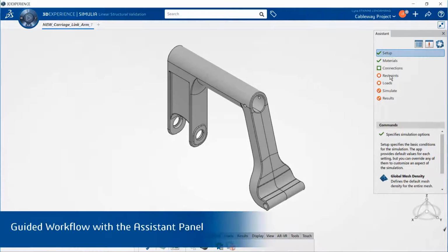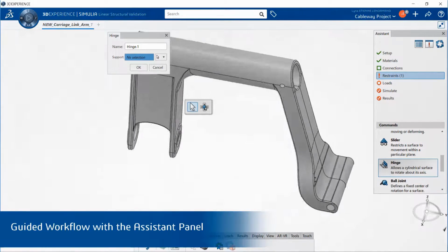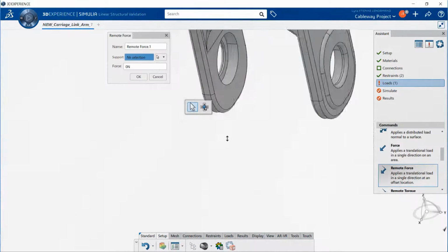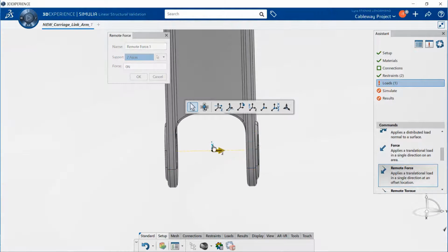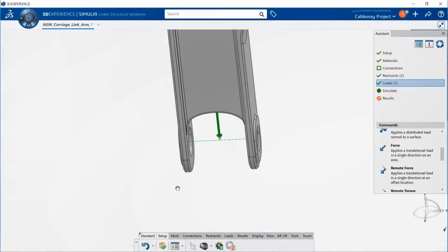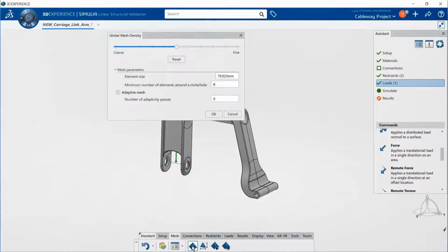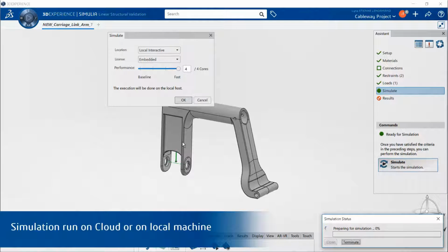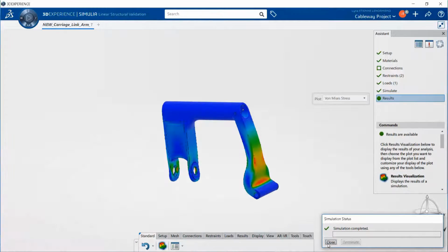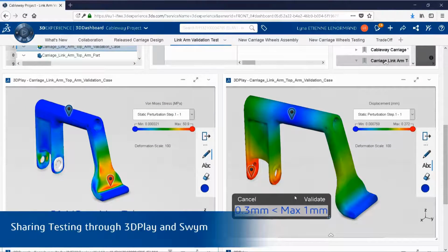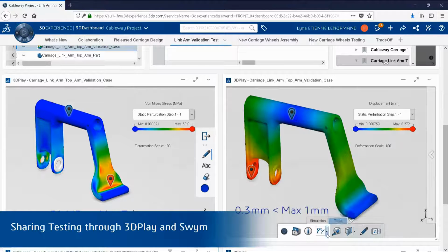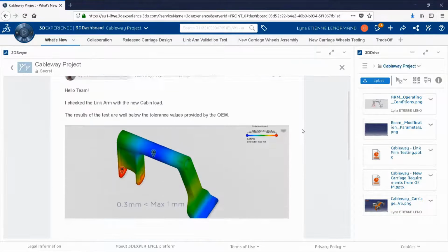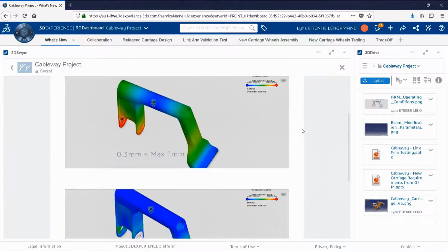So I want to do a structural simulation. You have the geometry here. Material properties are directly imported from the CAD. We're having nice pictures to explain to us what the boundaries are that we are specifying. And this makes it really easy to use. And this is allowing a designer to easily run simulations himself. It's not about the digits in percentage to achieve exact results. It's about getting an idea. How are my displacements, my stresses, where do I have peak loads, to better understand my design and to easily decide, do I want to go for option A, B, or C, if I'm having different ideas.